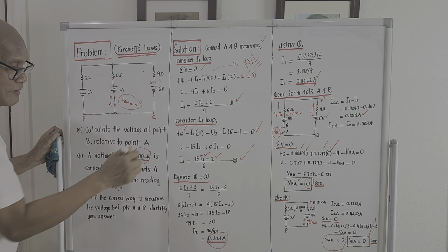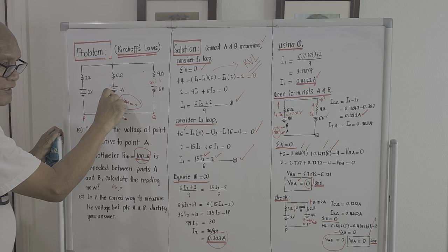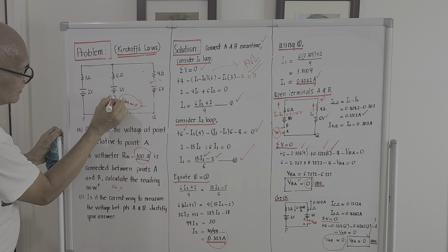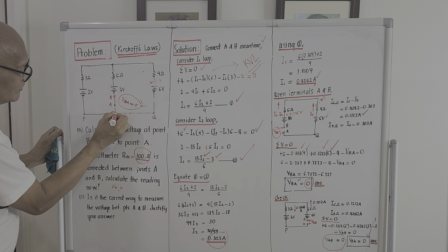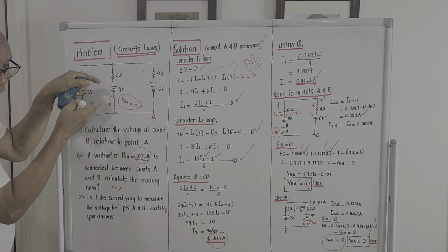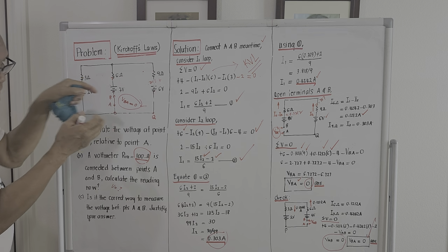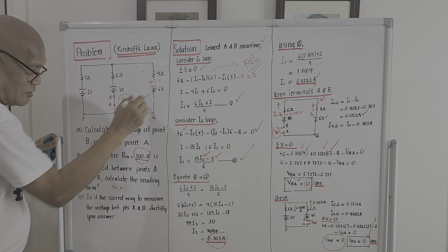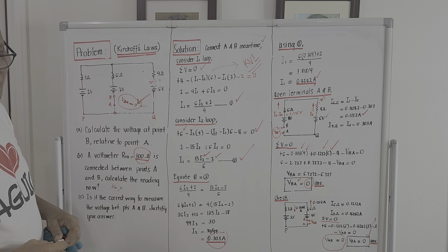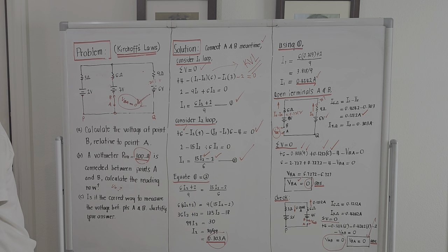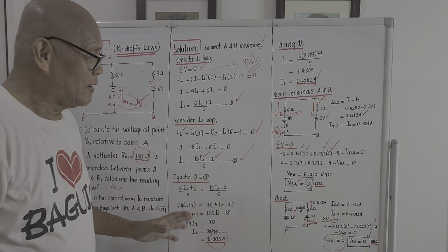And we have proven it that the voltage across this by using Kirchhoff's voltage law is actually 0. Because this is a ground and this is a ground. So if you put your resistor here, they are at the same potential, right? So the voltage will be equal to 0. That is by just inspection. I think this is a qualifying exam. Maybe I don't know where Mr. Veracruz got it. Okay, that's it, guys.